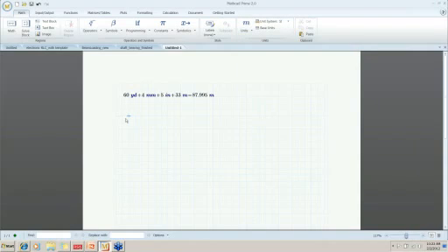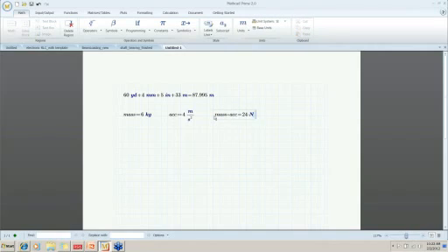As another quick example, if we define mass and set mass equal to 6 kilograms, and then we set acceleration equal to 4 meters per second squared, and this is really an example for the benefit of those who aren't familiar with units in Mathcad. If we type mass times acceleration, we get a result of 24 newtons. The math engine knows what the relationships are. It knows when you multiply kilograms times meters per second squared, you get newtons.